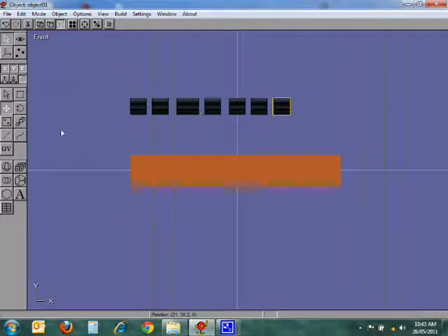You're pushing the crosshair tool. That's the crosshair tool, for which you need to first select the object, push the crosshair tool, and then carefully put those windows. You can adjust them very carefully so that you don't have to copy and paste more of those. Just select it and then adjust them. That way you have windows on the entire floor.